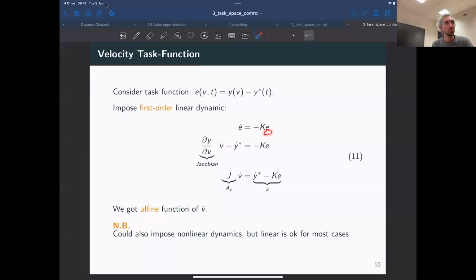Even though I've been working my whole life with these linear feedbacks, and I've never felt I needed anything more. Maybe some saturation at most. You may need some saturation if you have a scenario in which the error can get very large, you want to avoid then asking for a too large acceleration. Having some saturation on this error term would make sense, but it's not strictly needed, in my opinion.